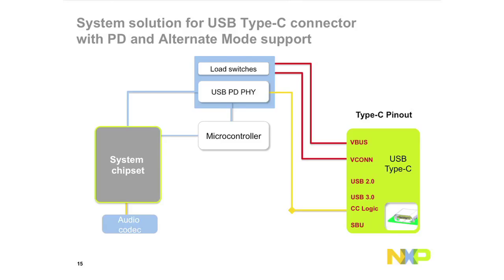So it is essentially an over voltage protection, over current protection, reverse current protection type of device for your own security. And same use case if you're a power provider, to be spec compliant, you want to make sure that you are putting out the right amount of voltage and current. So it is a use case for both directions, right? So appropriate load switches will be needed depending on the use cases.